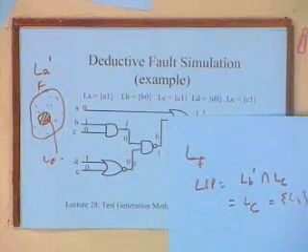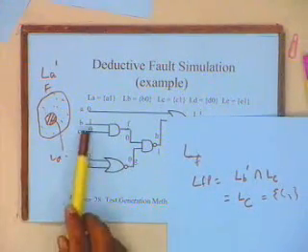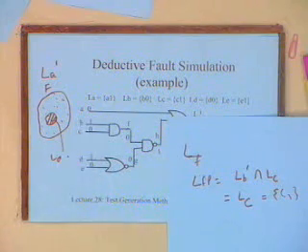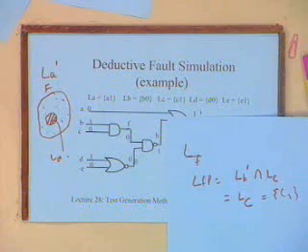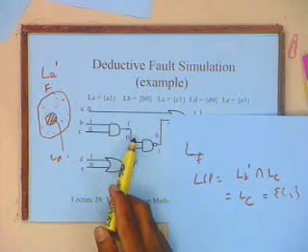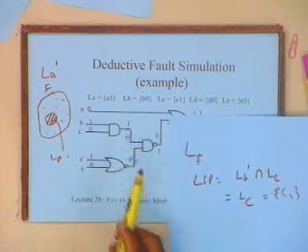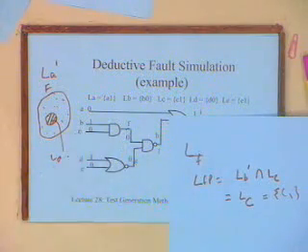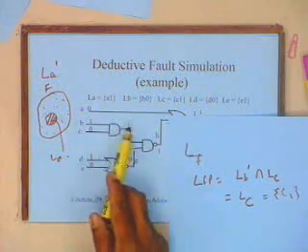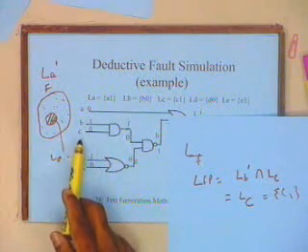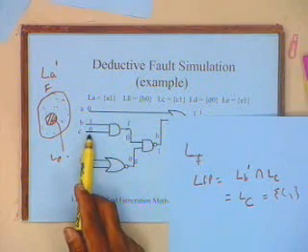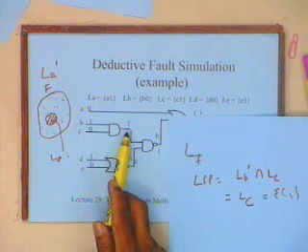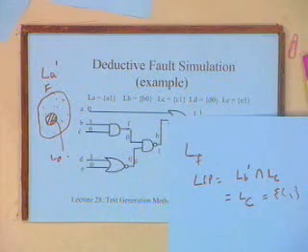So the fault that is propagated is C1, and you can see how this works. Why is the fault on B not getting propagated? If B0 occurs, the output would not have changed; F would still have been 0 even if B was stuck at 0. So this fault is not getting propagated. The only fault that gets propagated is C stuck at 1; if this fault actually occurs, then the output value is different, and this is what it evaluates.